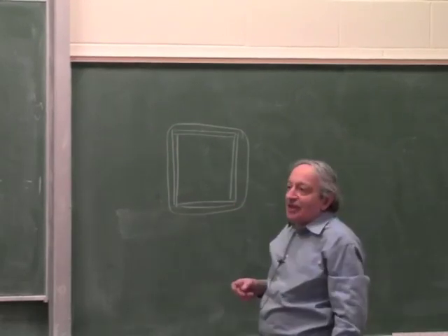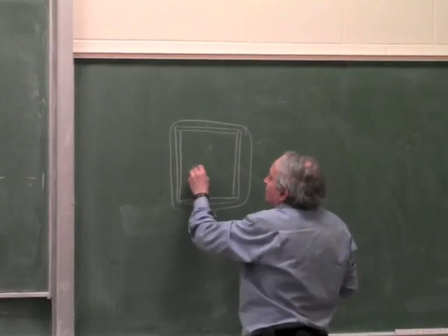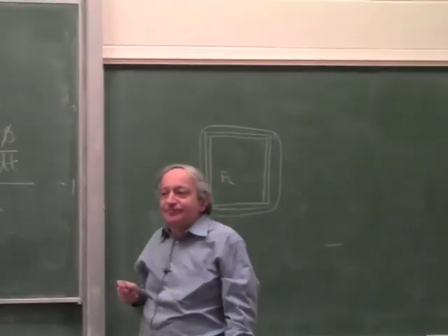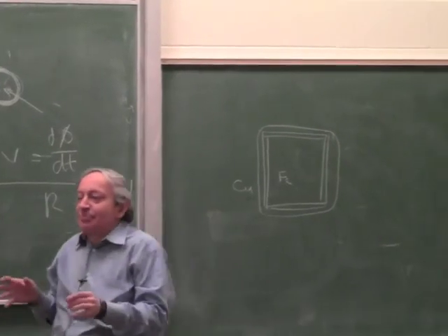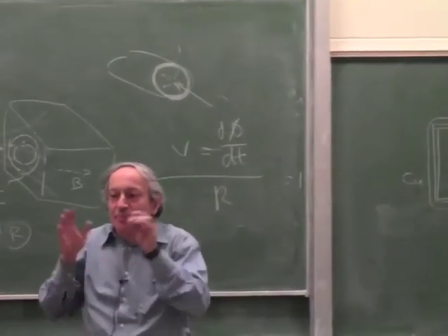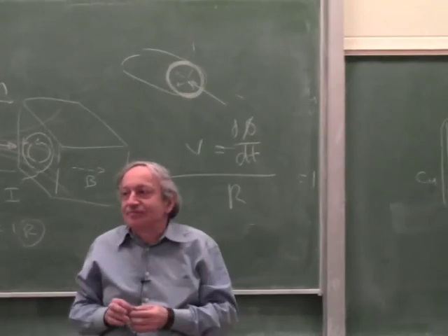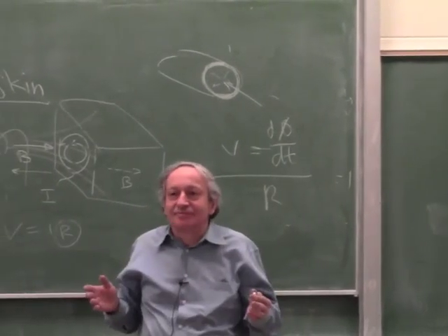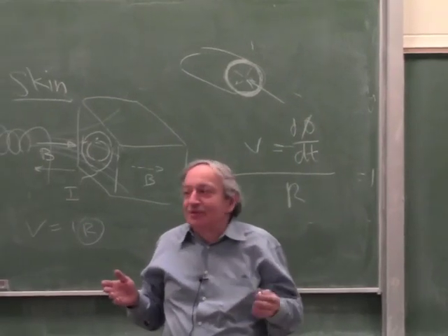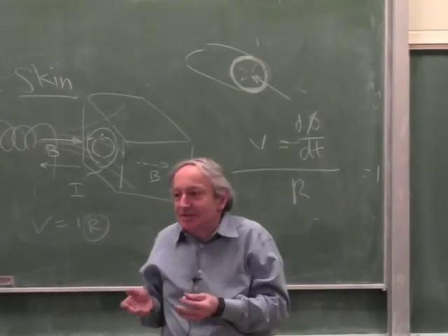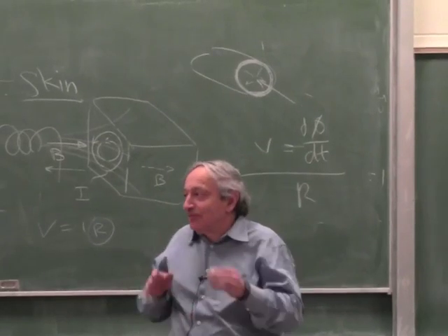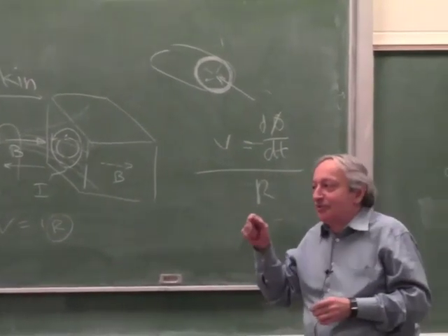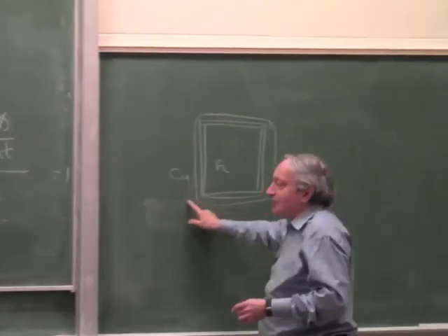Now, what is better, to put the steel inside and copper outside, or the other way? If you look at these boxes in instruments, it's always copper outside. Why? Very simple, nothing to do with shielding. Steel rusts, copper doesn't. So it's better to put the copper outside so it's protected from rust. Also easier to solder to. When you want to ground it, it's easier to solder to it.